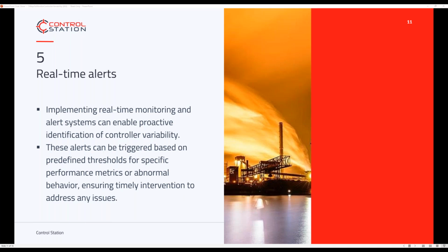And so when you're understanding alerts, try to treat them with the same respect as alarms, right? Any alert that gets generated should have an action associated with it. It's not just an alert for alert's sake to let me know that, hey, 500 controllers are in the wrong mode today. Great, I'm not going to do anything about it, so that was worthless, right? So make sure that you treat the alerts with that same requirement, that there is documentation, there's a procedure, there's an action to take place on those alerts. Make sure there's accountability for those alerts, right?